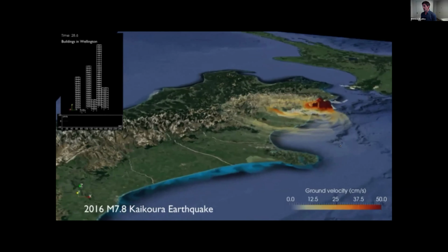And it's particularly important in the context of, for example, what Thalia again was showing, where if you're going to do any type of dynamic analysis, you need an estimate of the ground shaking and how it varies with time. And so we have that usual what we call ground motion selection problem. Through these methods to simulate ground motions directly, you actually get the time series of acceleration, and therefore you avoid the problem of having to select a compatible set of ground motions consistent with your seismic hazard.